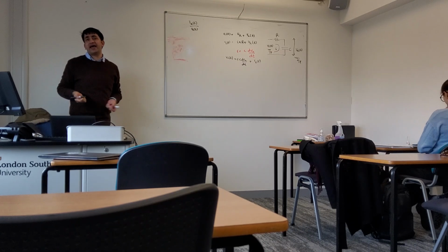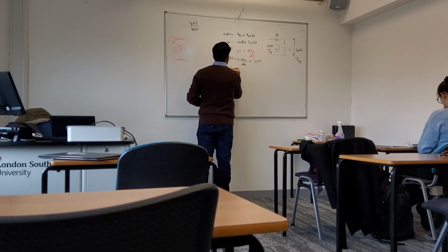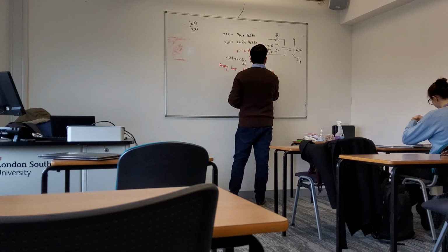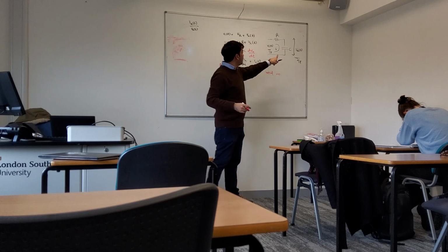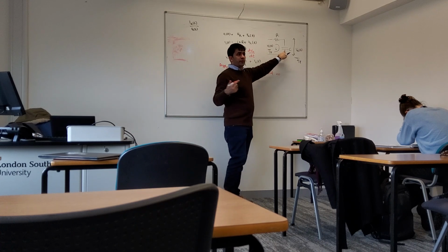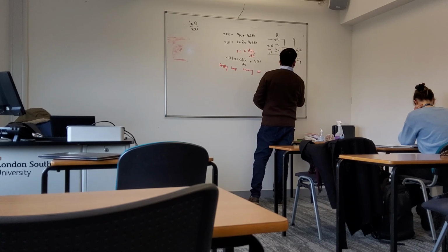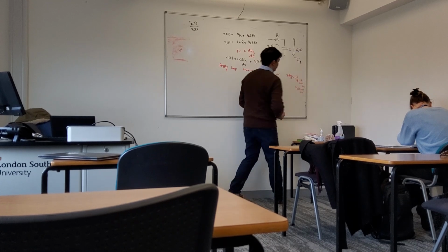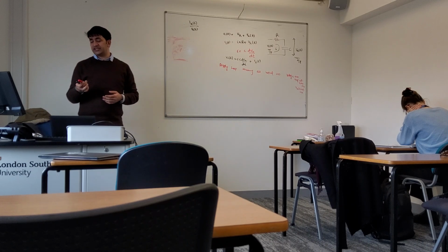Now we can apply the Laplace transform, right? So let's apply the Laplace transform, assuming all initial conditions are 0. What does it mean? It means that there was no voltage across the capacitor, so the voltage across the capacitor at t equals 0 is 0. This is what we said: when we find the transfer function, we will consider that the initial conditions are 0.